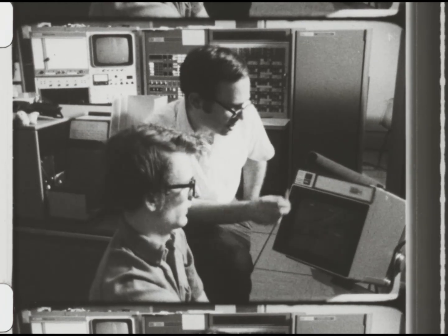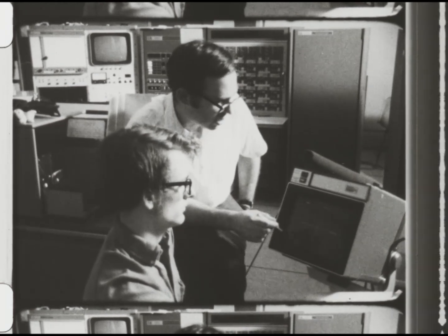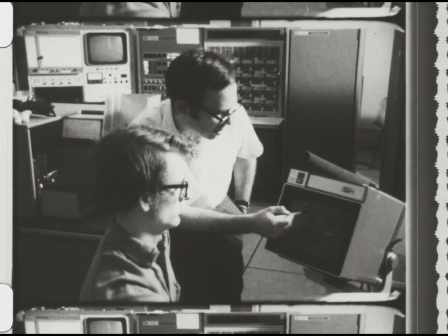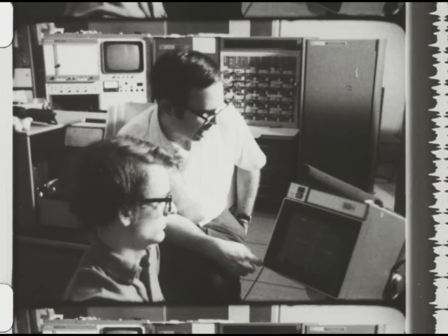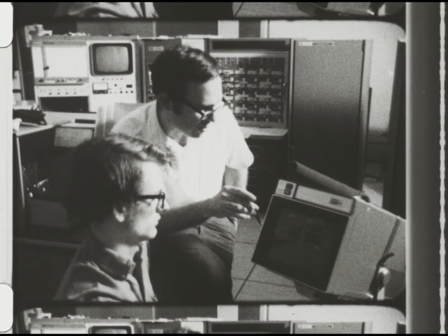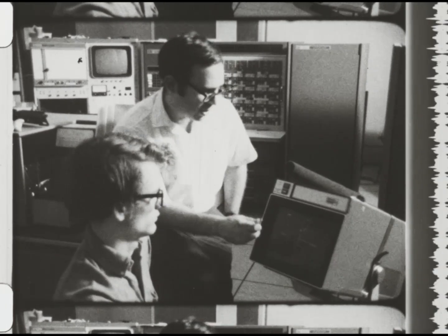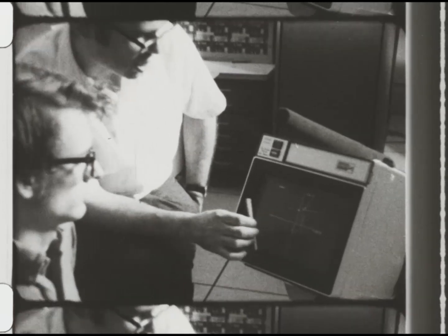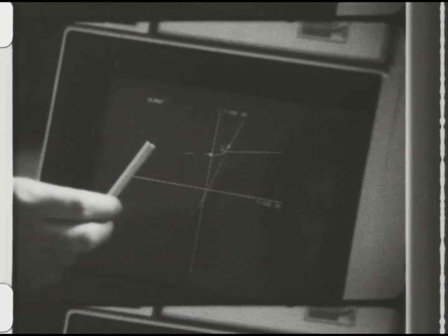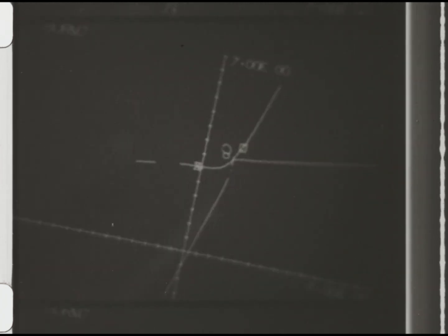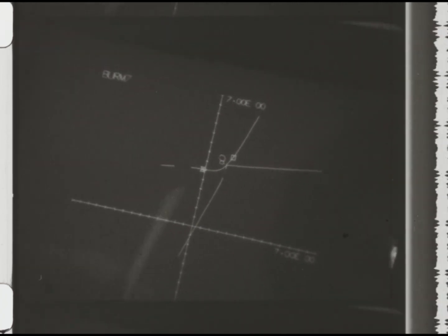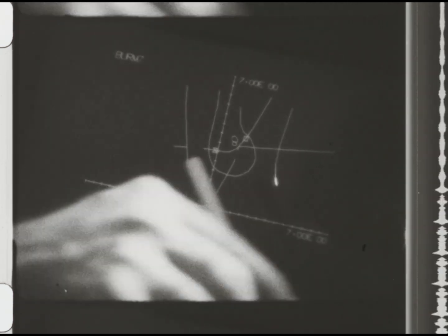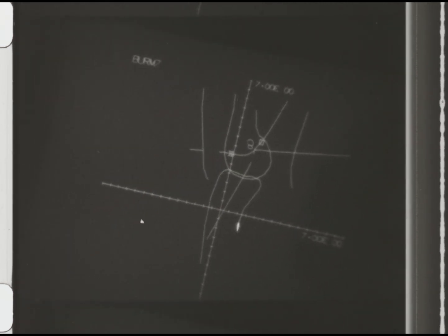For 4 specified design positions, there's infinite loci of possible circle points and possible center points. And these curves are different for each specified motion. It's important to recognize that this is a synthesis program. The input data here was not the design of the mechanism, and we weren't looking to see how the mechanism behaved. Instead, the input data here was the kind of performance that we required, the precision positions for this mechanism.